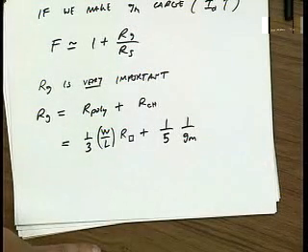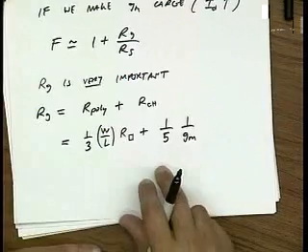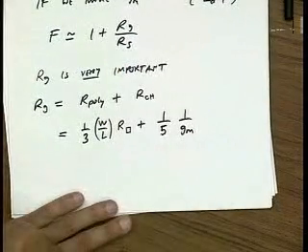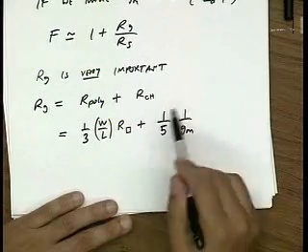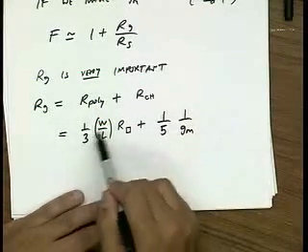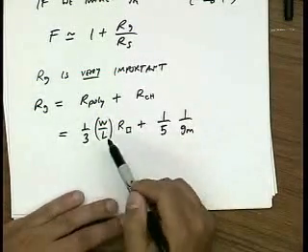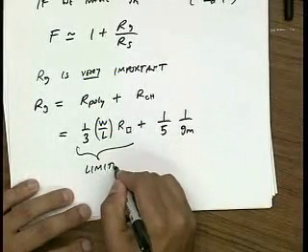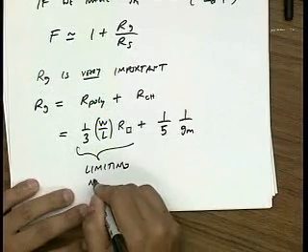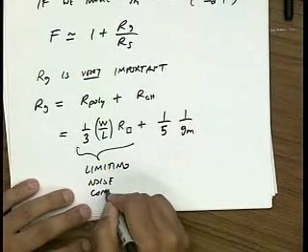So this is a long channel approximation. Again, you can see that if you make GM very large, this component starts to become negligible, and just the physical resistance of the gate starts to dominate. So this is the limiting noise contributor.